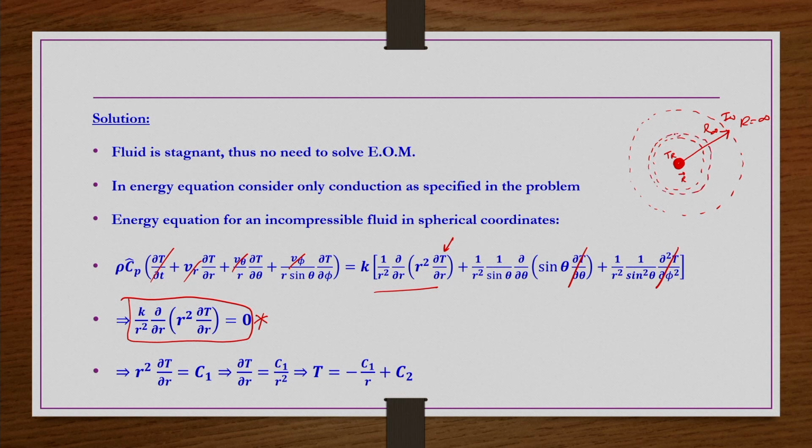So, this is the volume element in the spherical geometry, whose thickness is dr. So, let us say the radius of this element is small r, and the radius of the outer surface of the element is r plus dr. So, the thickness of this element is dr. So, now what is the rate of heat entering in the r direction because of conduction, minus the rate of heat leaving in the r direction at r plus dr because of conduction, that you can write down, right, and then you take the balance equal to 0, because we are not taking any accumulation term here, steady state. So, then you get this equation, that way also you can do it.